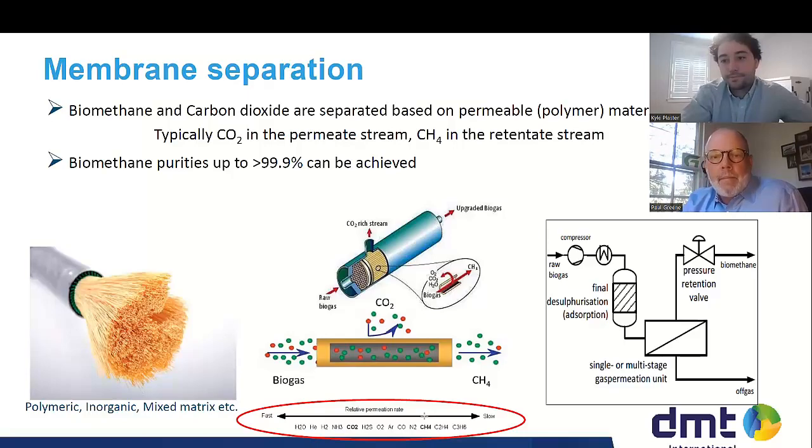Okay. And then along with that, there are certain pressure and temperature requirements. So a higher pressure will get better permeation, better selectivity, but there is a max because you don't want to actually blow out those membranes. And same with the heat. So there are limits there as well.